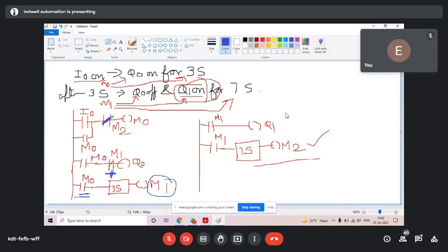So as you break latch, be very clear. As you break all latches, all your coils will get off. Means everything will be off. So don't worry. If latch is broken, see, I have broken latch. If latch is not broken, then it will not run in next cycle. So latch is broken, it means everything will get off, and in next cycle it can run. Okay, another question. If you have any, you ask me.